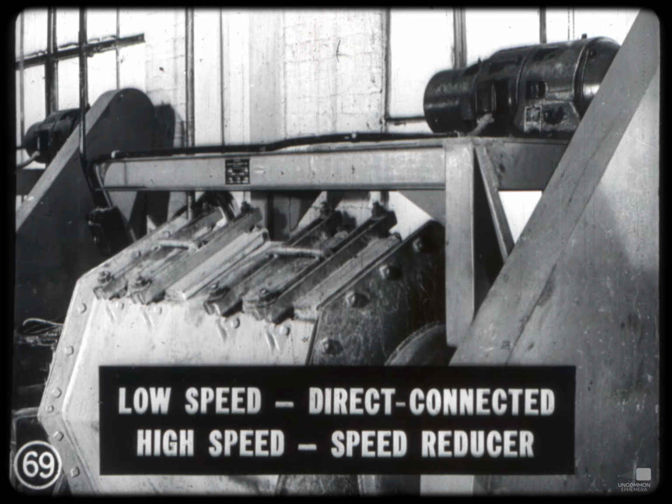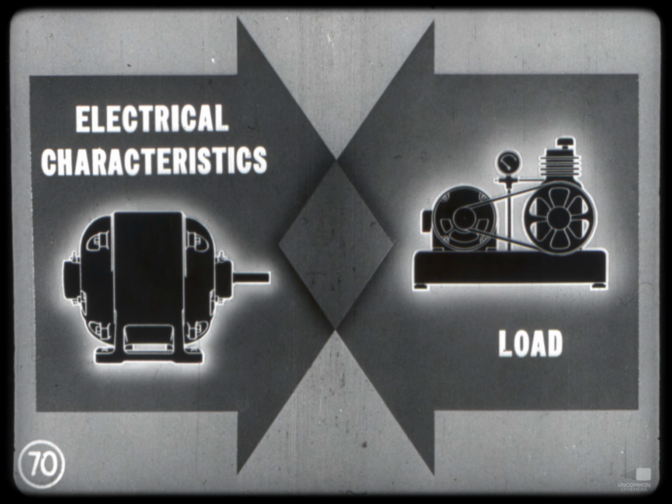On a machine such as this cement mixer, however, which runs at a speed slower than standard motors, it's good practice to make a cost comparison between a low-speed direct connected motor and a high-speed motor with some form of speed reducer. Before final selection of a motor, the application always should be checked to make sure the electrical characteristics of the motor suit the load of the driven machine.